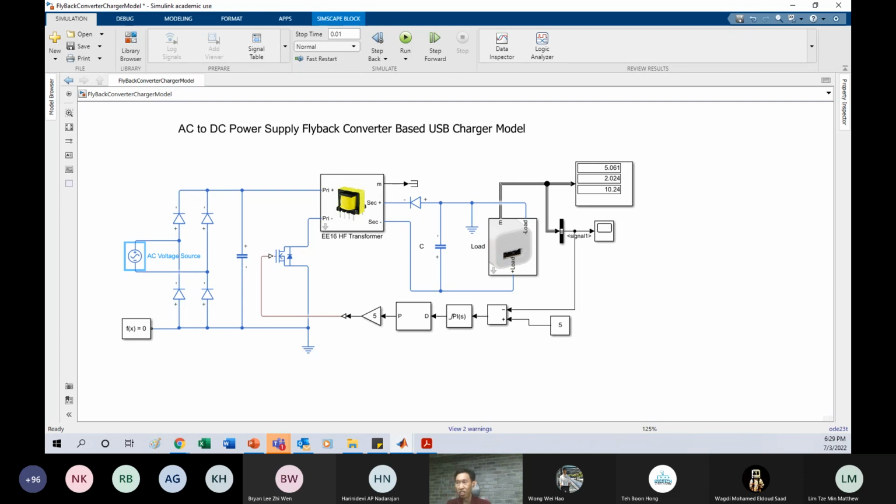This is the complete one. In fact, this is a combination of two converters. This part is the AC to DC, which I have not yet taught but you already know. And this part is the DC to DC converter. Even though you put a buck here, it will work. The only thing is that there's no insulation. That means there's no guarantee of safety. You may have some AC flow through your phone, or you get electrocuted, I don't know. That's why I always have this one.